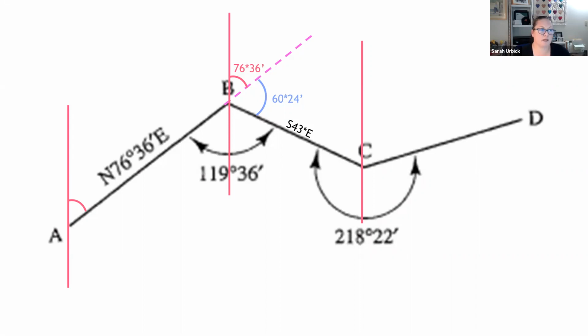All right. So this next one got a little tricky for me. This one's a little bit harder, right? Because what we're given is that exterior angle. We're given such a large angle there. Finding that value off of C is a little bit tougher. But what have we learned so far? We know that that angle is now 43 degrees. Our angle between B and C and our south is 43 degrees. So what other angle is 43 degrees?